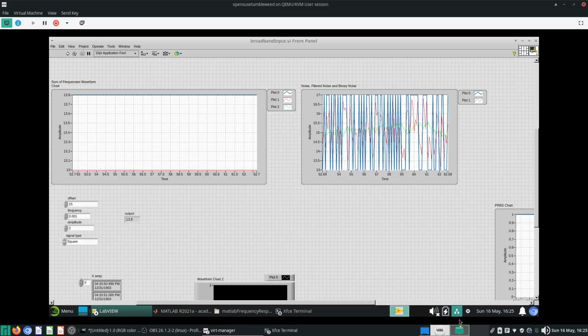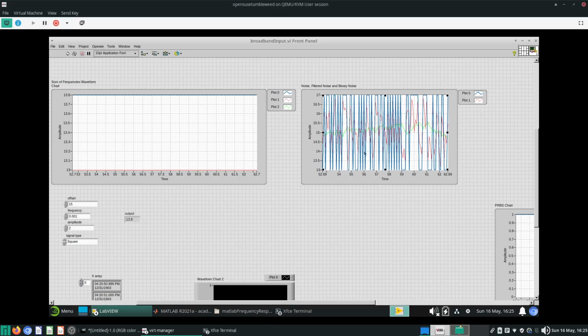Now that's all well and good, provided that your controller can actually vary the input like that. If your controller cannot vary the input up and down like white noise, then you're going to have a problem. If your controller is slow in response, then you cannot have a white noise signal as a test input to do a broadband frequency response test.